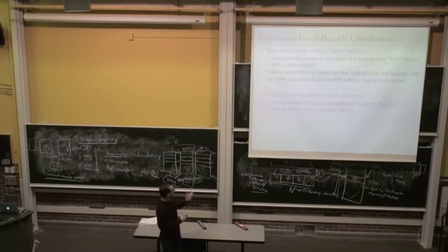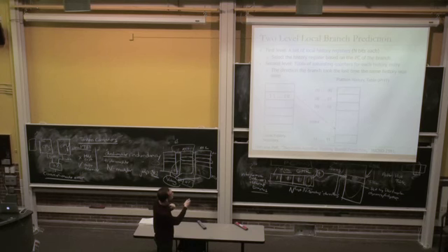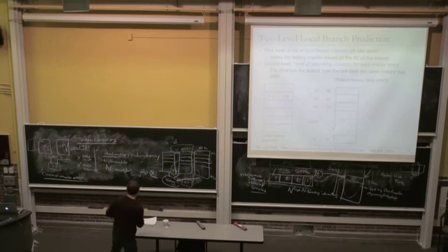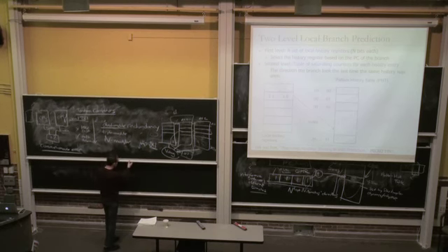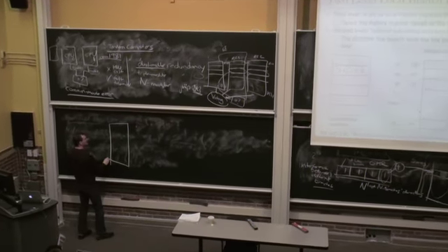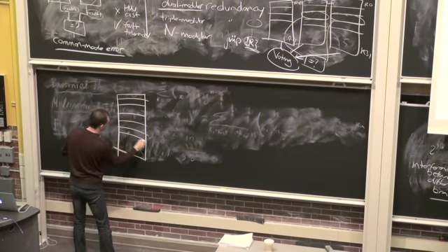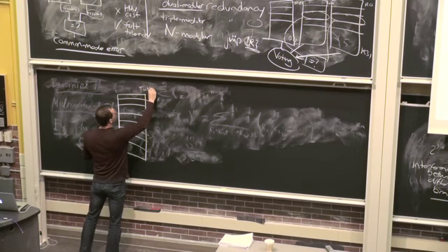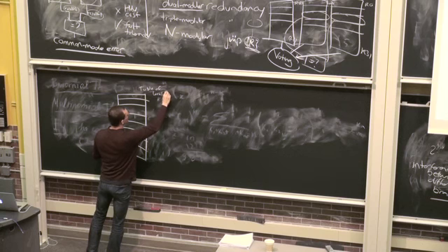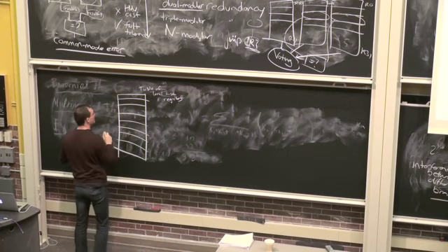So, okay, how is this different from the global predictor? Well, one implementation is like this. Basically, instead of having a single register updated by all branches, you have a bunch of local history registers, right? And that's the idea here. So how do you index into it? So this is a table of local history registers. And remember, we want to do this per branch. We want to keep the history per branch.